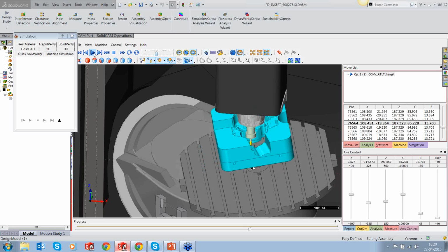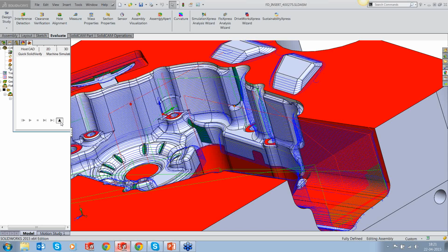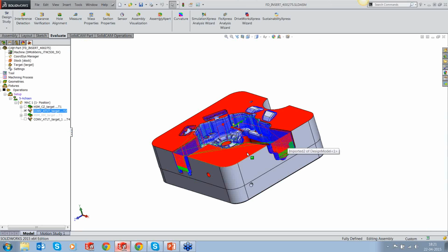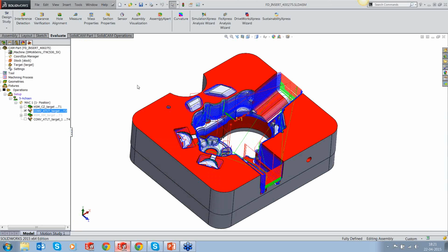So you can see that it's tilting both the axis C and B. So what it basically did was to take up the complex HSM toolpath, just apply new tilts, do the gouge check, everything automatic within the system. We did not have to intervene into the system. It's one of those few systems that does most of the things automatically by itself without having to specify anything.